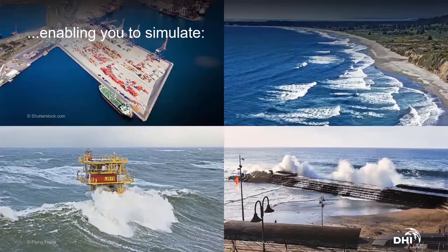With this software, you will be able to simulate both the cases that you are used to simulating, such as wave harbor studies, but also some of the very nonlinear phenomena such as wave overtopping, nonlinear shoaling, diffraction effects, and reflection effects. Previously, with some of our MIKE 21 BW models, we would have some limitations on the water depth, which in this model you don't have.